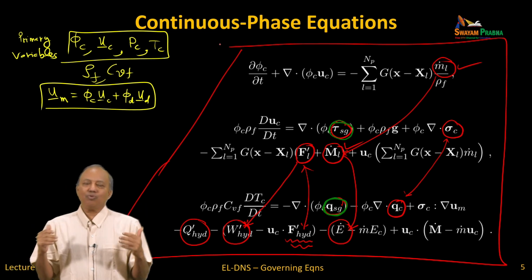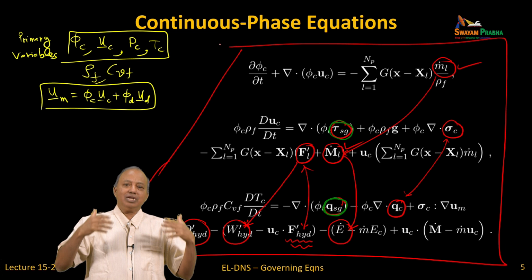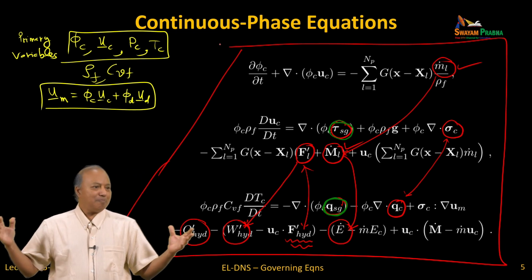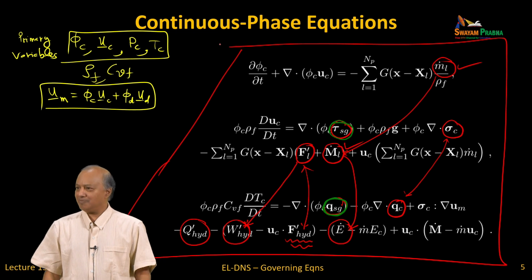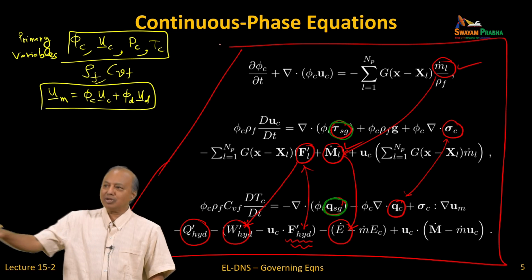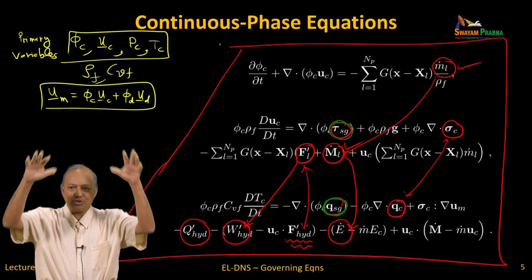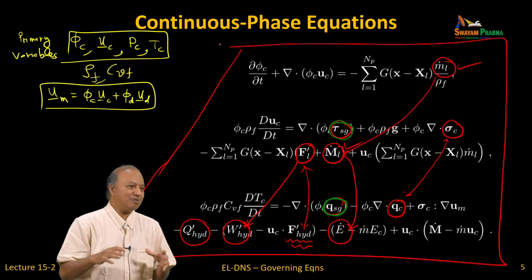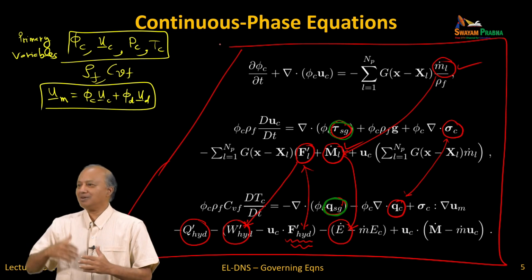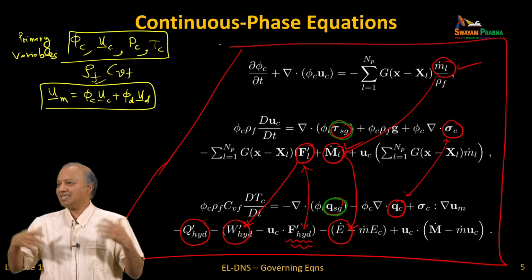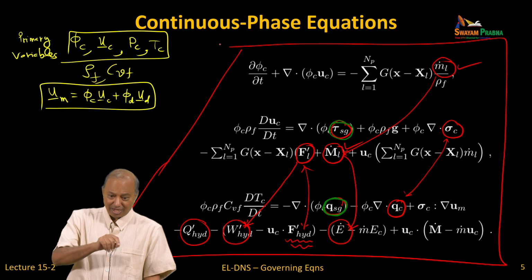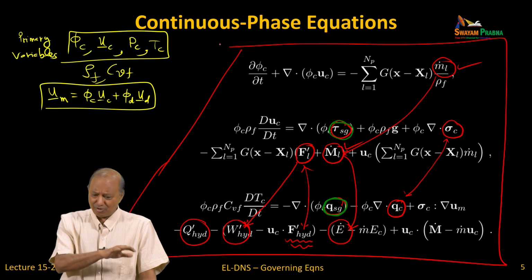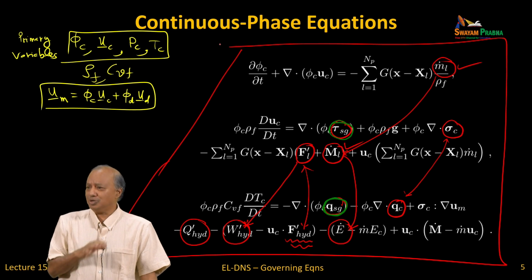So in other words, the way to think of this is the real flow is in a trillion dimensional space. It's really complicated. When you do Euler-Lagrange, you are saying I am projecting it onto a much smaller space. That smaller space deals only with big eddies. What is not on that space is small eddies. The question we are asking is, on that reduced dimensional space on which we are computing, am I doing a good job?